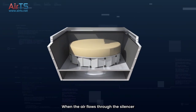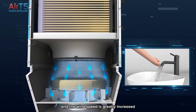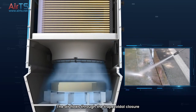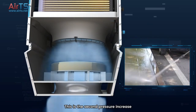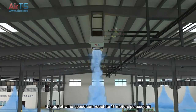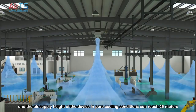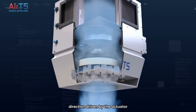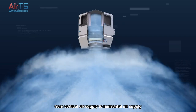of fluid mechanics. When the air flows through the silencer, sponge, and tray components, the wind passing area is sharply reduced and the wind speed is greatly increased. This is the first pressure increase. The air flows through the trapezoidal closure, and the entire lower part of the device has a trapezoidal closure structure. This is the second pressure increase. After two pressure increases, the outlet wind speed can reach 16 meters per second, and the air supply height of the device in pure cooling conditions can reach 25 meters. The 12 guide fan blades at the air outlet can rotate in the same direction driven by the actuator, which can realize stepless adjustment from vertical air supply to horizontal air supply.